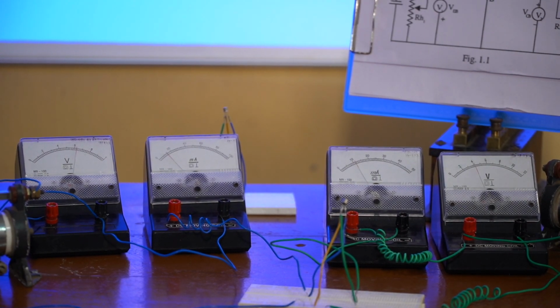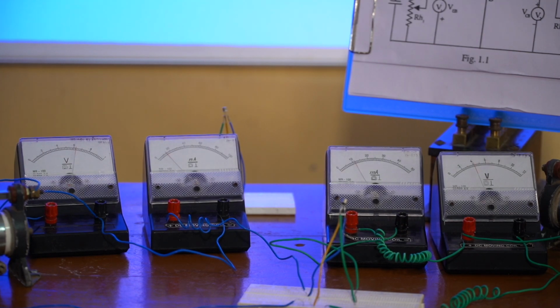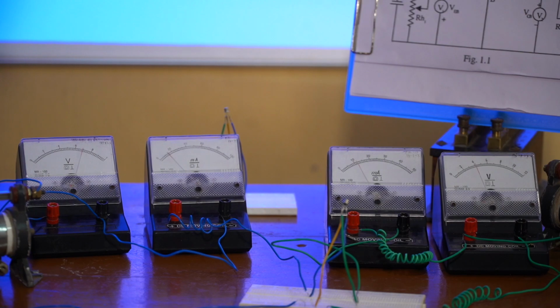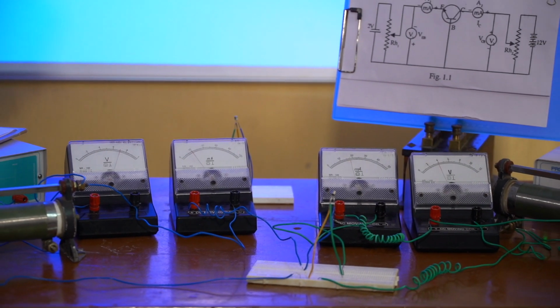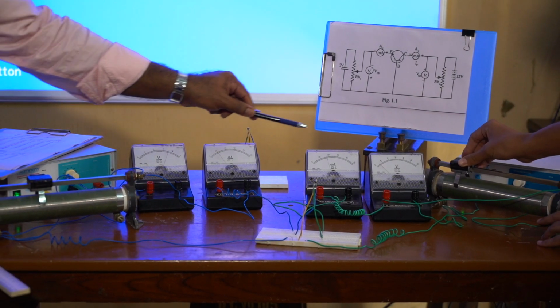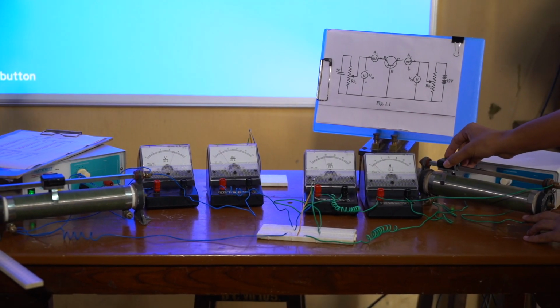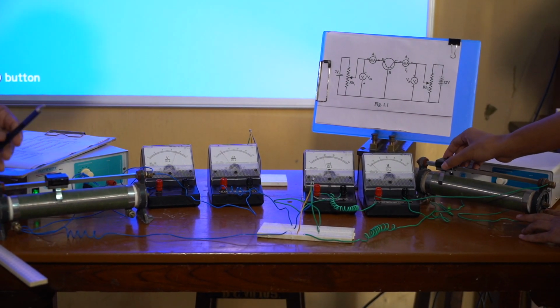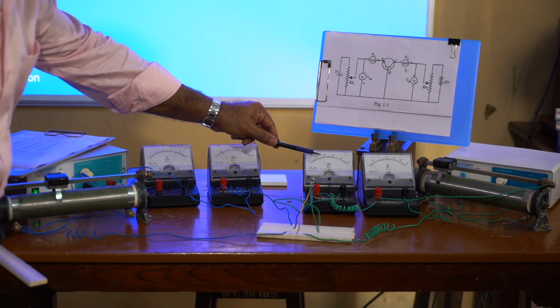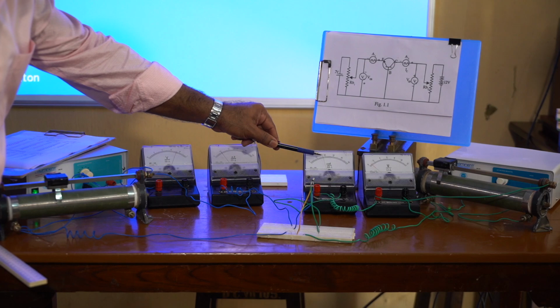Now, we can repeat it. For repeating, we are changing the input current. The input current is changed, say to a value of 20 milliampere. So, the input is kept constant. Now, change the VCB value. So, take the VCB value 0.2 volt. Now, for 0.2 volt, it is reading a value of nearly 17 milliampere.